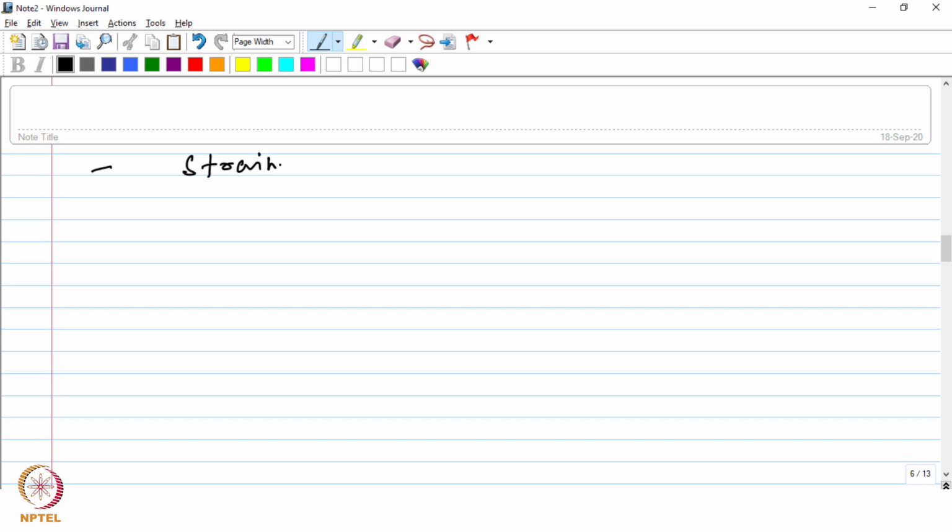So right now, when the material is in cold worked state, you have these strained grains with high dislocation density. So across a boundary, if there is a difference in the dislocation density or in the strain energy, then the region which is of lower strain energy can actually bulge into the higher strain energy region, and a small bulge can form which will be free of strain, and that can act as the nucleus.